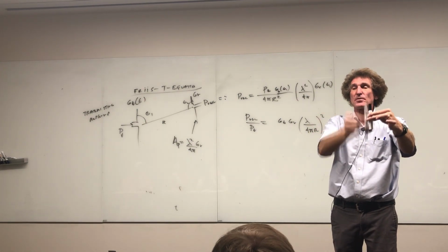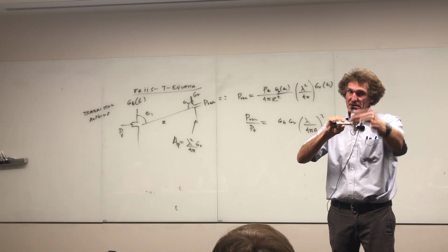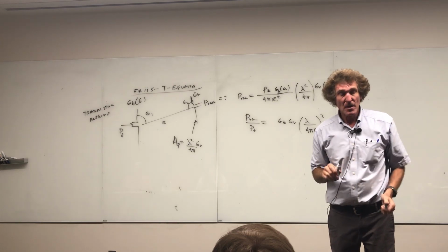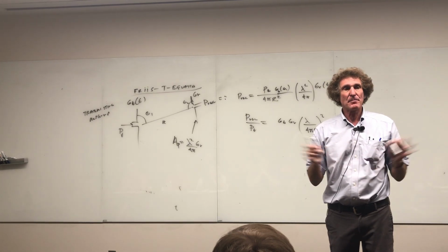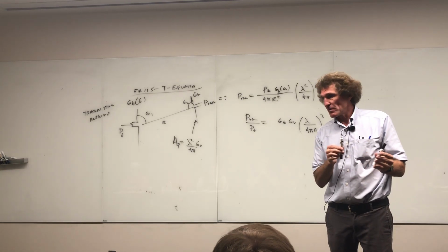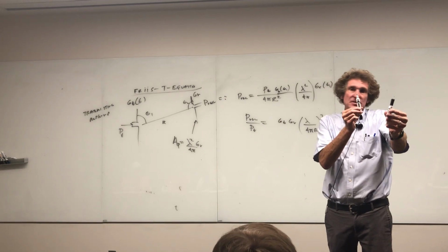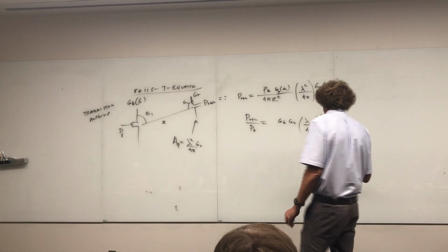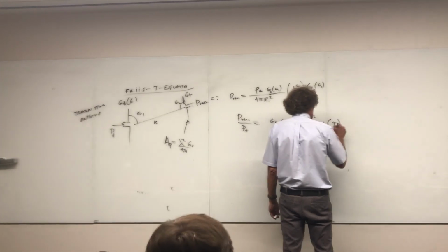This receives vertical signals. So there is no component of the electric field from this one in this direction, and it's 0. This is called polarization mismatch, and it happens all the time. Almost invariably, you can't help it in the real world. You're going to get some polarization mismatch. It's just reality. So the way it works is you take the cosine of the actual angle and square it.